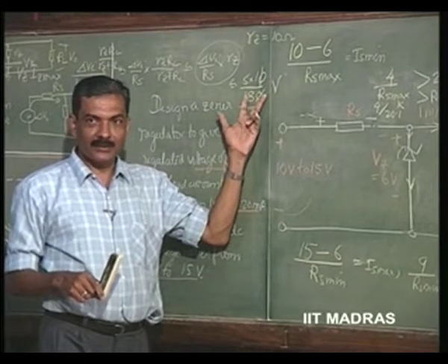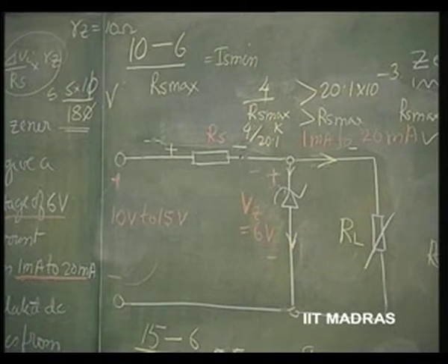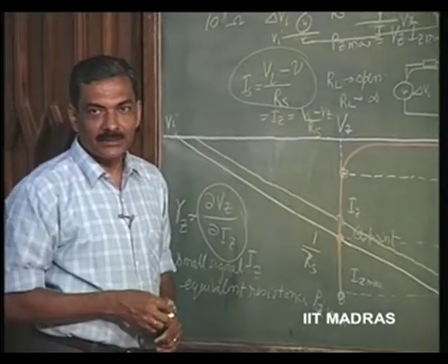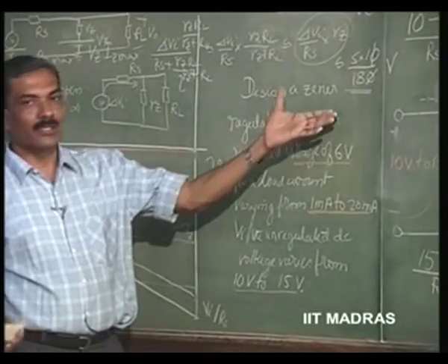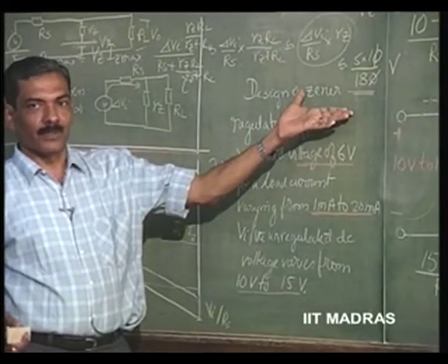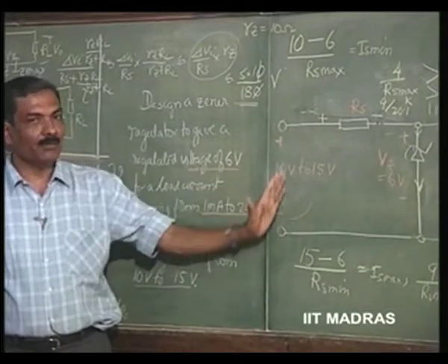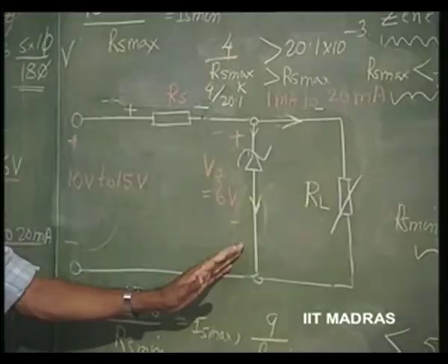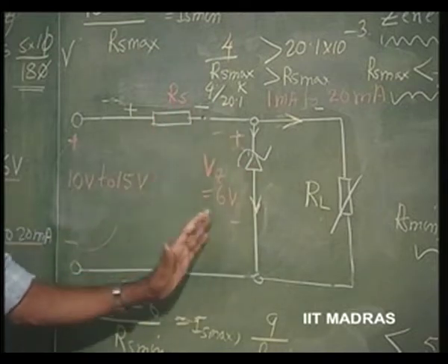It has a series resistance of Rs. Because of that, when there is a change in voltage, there is going to be a small change in voltage here, in the Zener. That is the delta Vz, and that we could calculate by using the equivalent circuit for the diode. So, if somebody says that the voltage changes by this amount here, we can always find out what the change in voltage is, which is extremely small, around the Zener voltage, by using the Zener equivalent.